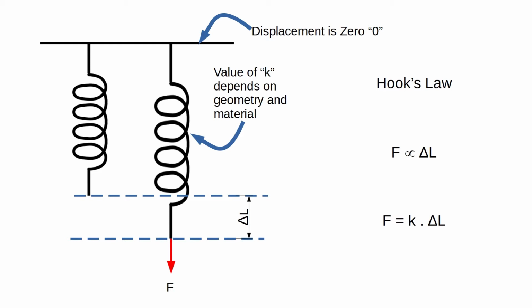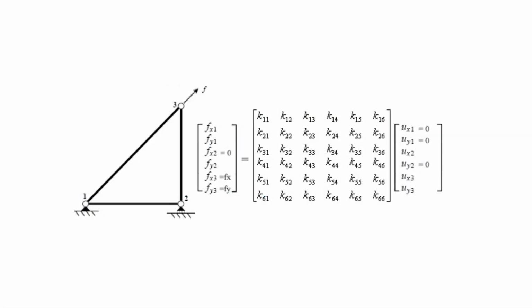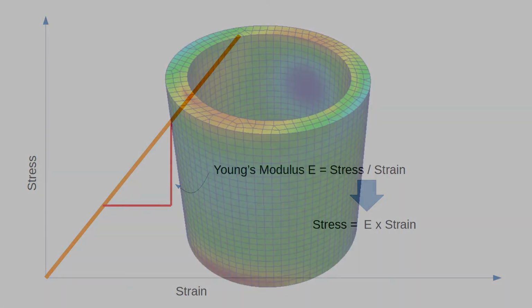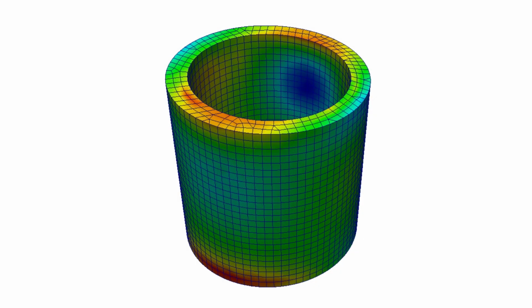After all of the above is given to the finite element analysis software, it tries to solve the equation, which will be in matrix form, with the given input values of displacement and forces, and obtain displacement for the entire object. These displacements or strains are converted to stresses. As we know, stress equals strain multiplied by Young's modulus of the material for an elastic case. These stresses are then displayed as a colored model, or they can be exported as a table.